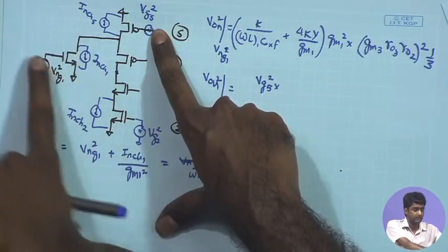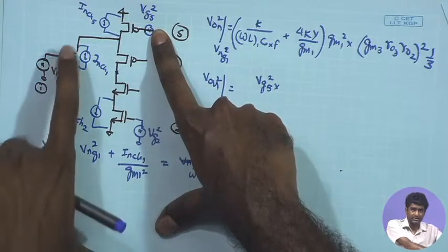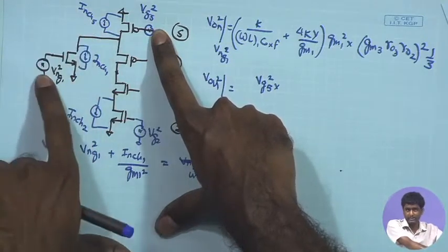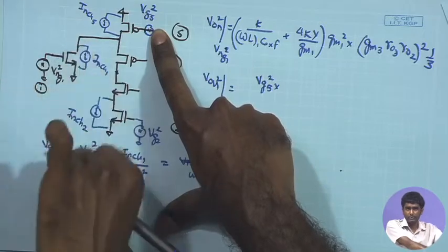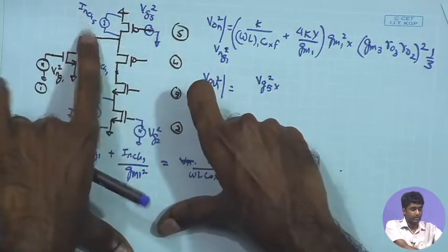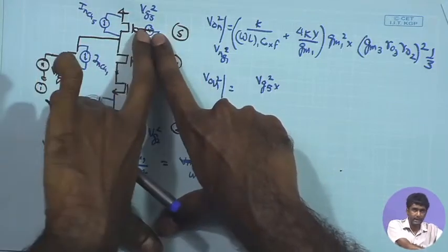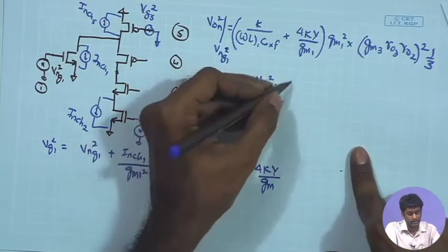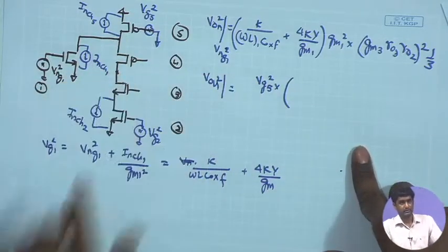So, when we are analyzing the effect of this VG5, we are ignoring this branch. Why? Because the input signal is 0. Therefore, you have stacked transistors, 2 NMOS with gate voltages at AC ground. Therefore, the impedance looking into the drain is GM-RO square. Here it is just RO, and therefore, I can ignore this safely. So, I ignore this, and therefore, this is our simple cascode amplifier with input signal at this PMOS, and therefore, the input signal is VG5 square, and that I have to multiply by the gain of this circuit resulting from this amplifier.